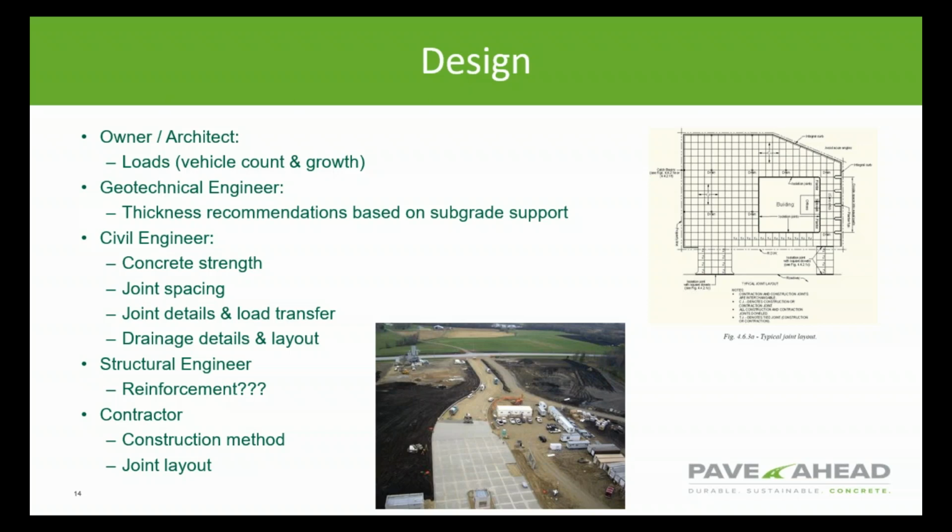The geotechnical engineer typically provides thickness recommendations based on traffic and soil data gathered. While these may be considered recommendations, civil engineers rely heavily on this as a design. So it's very important that the geotech use appropriate guides for design. The civil signs and seals the plans whether or not they're providing the actual design. Civil should be knowledgeable of the concrete design.